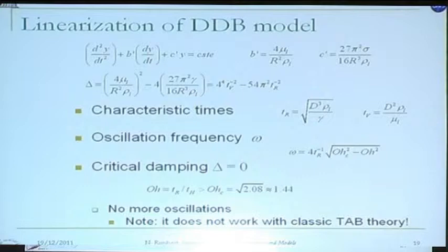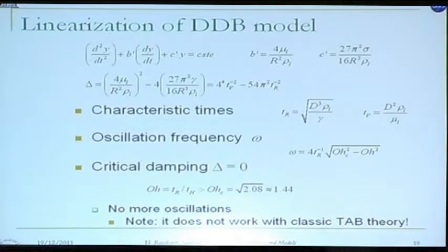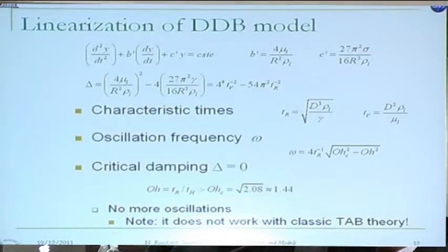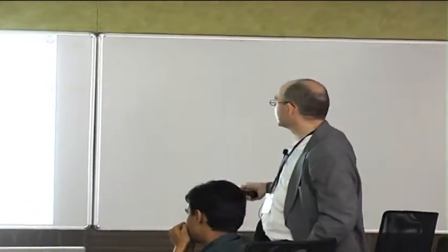If you don't have oscillation, it will be very difficult for a Rayleigh-Taylor instability to work because the instability will be damped very quickly. So here you are in a stability region as far as Rayleigh-Taylor instability is concerned. The wavelength of the related instability is given by this formula. Here you have the surface tension, the difference of density between the liquid and the air, and here the acceleration of the droplet. But when the droplet is falling, the droplet is decelerated, and you can have a classical formula for the drag of a droplet.